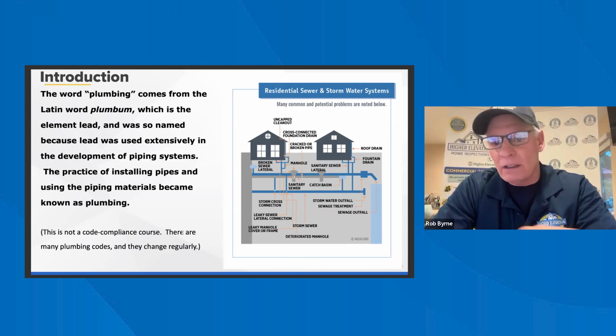Bathtubs, shower enclosures, you tap around to make sure that the tiles are in good shape, because sometimes there could be hidden moisture damage behind there. Whenever we do a house and we come across tiles where you're tapping on it and you hear them clicking or loose, water got back there. So what I would do is document it in the report, stating loose bathroom tiles, check for hidden moisture damage. Because once they start taking those tiles off the wall, there's going to be hidden moisture damage in there. So little minor things like that, discuss with your clients to keep it caulked and sealed properly. Those are all important things.